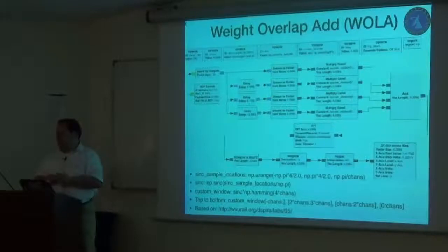There I'm limited to 17 kilohertz resolution, because if I want more resolution, it simply does not fit into the FPGA. And it turns out that for many of these sources, you want a little bit higher resolution. So you want to start using the FFT on the PC. And then you start getting the ability to use all these nice tricks to really get the most out of that FFT. Okay. Can you do that also in the FPGA?